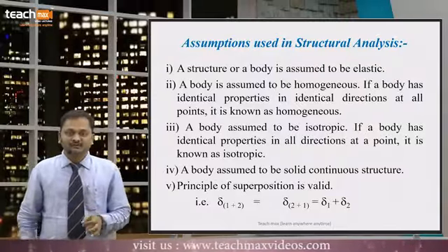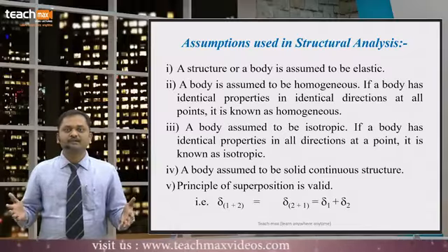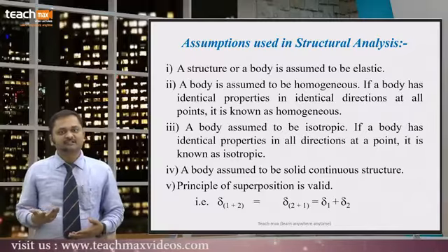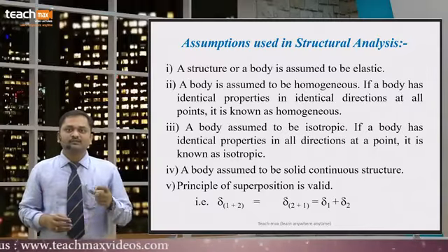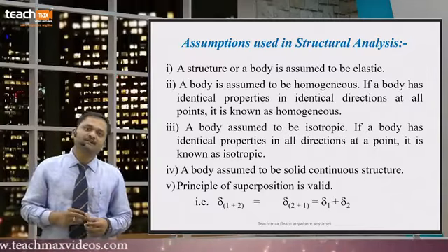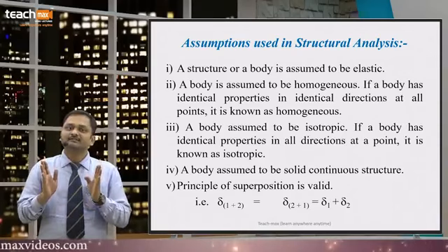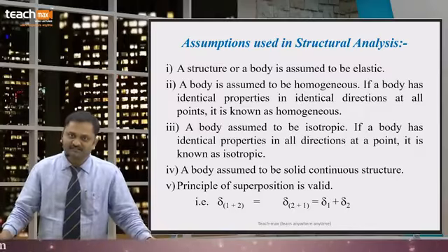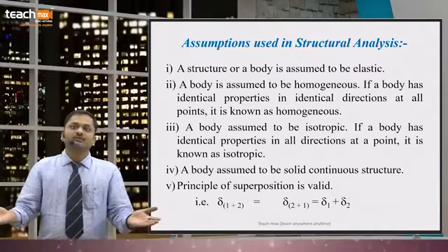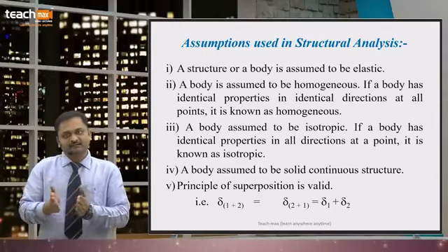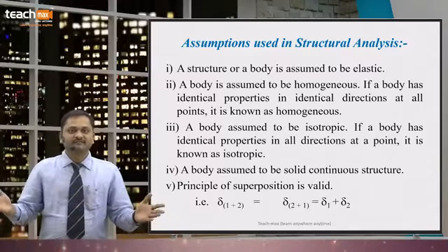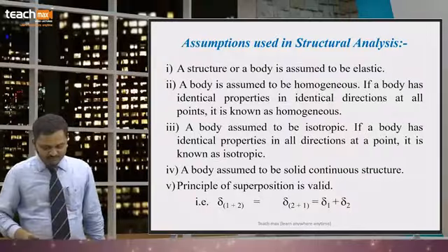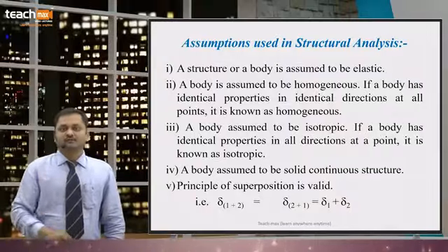If a body is subjected to, suppose, two forces which develop some deflection, and you want to find the deflection at any point in the body, you can consider these two forces separately and find the displacement or deflection separately. If you add these individual effects together, definitely you will get the exact total deflection.